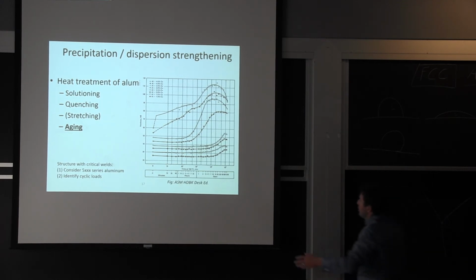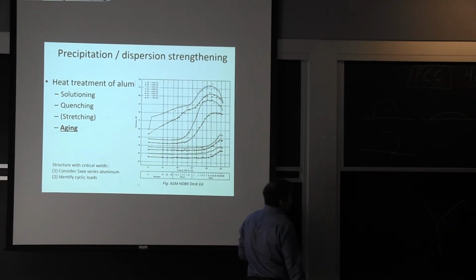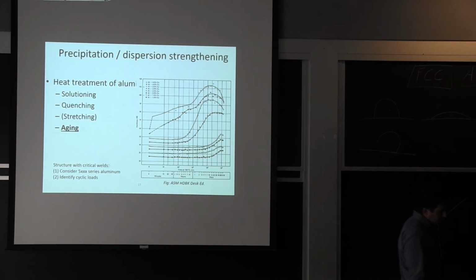When you're a little bit past the peak, the advantage there is typically pitting corrosion of aluminum in chloride environment. If you have your precipitates that are bigger and a little bit more separated, the energy of the grain is slightly lower, and you're just improving your pitting resistance. So it's just a question of exactly how you want to optimize it.